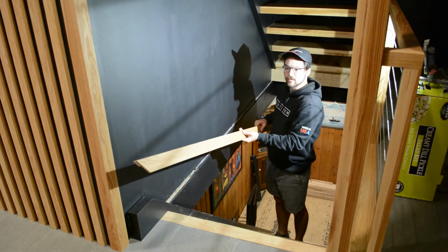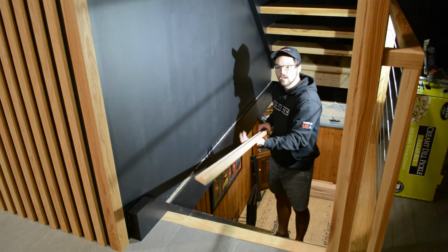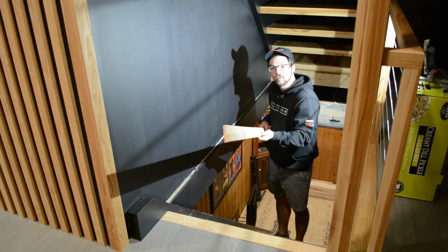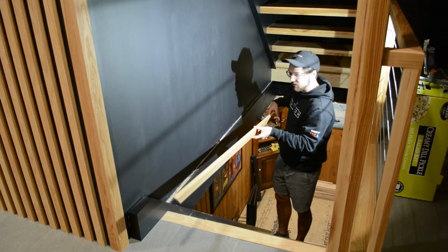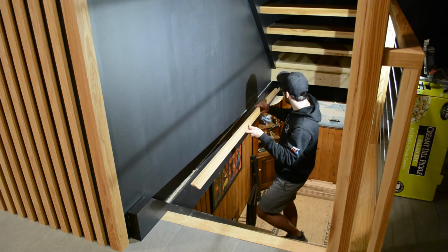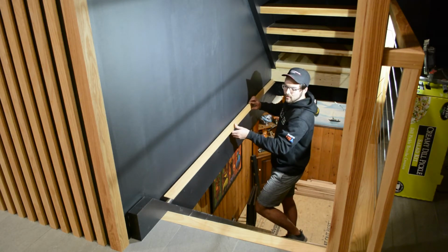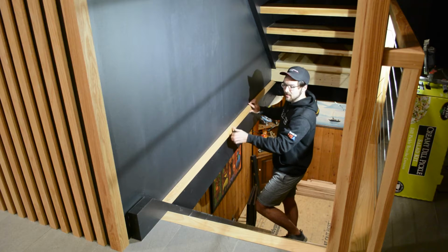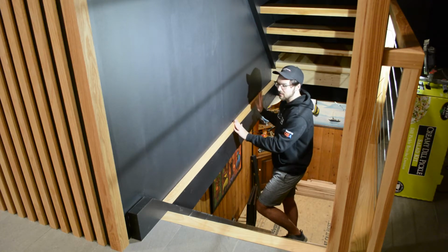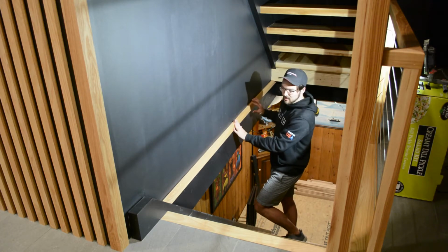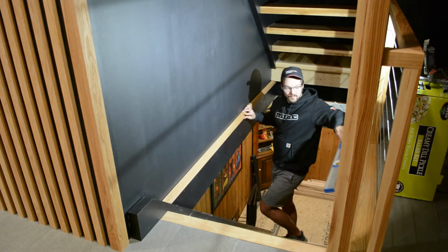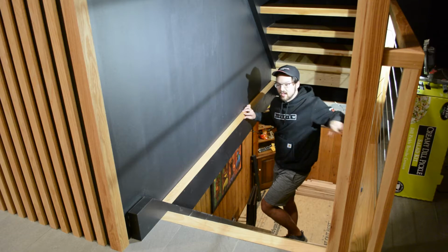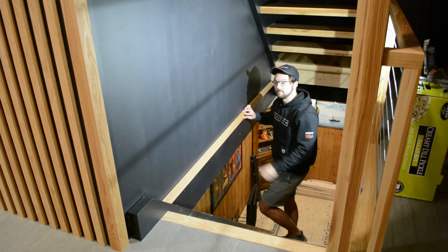All right, so I just finished cutting our actual board. As you can see, I got that profile carved in there with the table saw, and now it fits over everything really nicely. I'll show you a quick mock-up, just like that. And you can see it sits flush up against the MDF and covers up the seam nicely. So I'm going to make sure to put a level over it and make sure everything's nice and level, and then I will use my pin nailer to nail it into position.